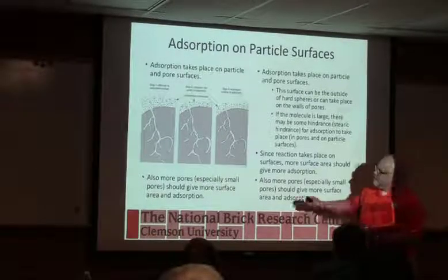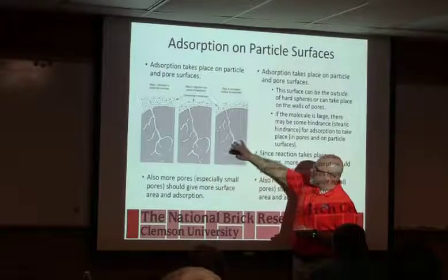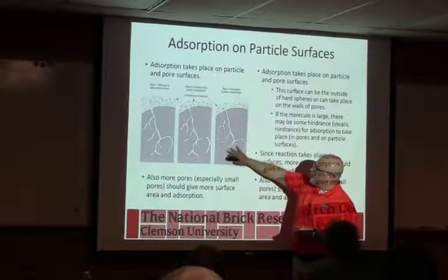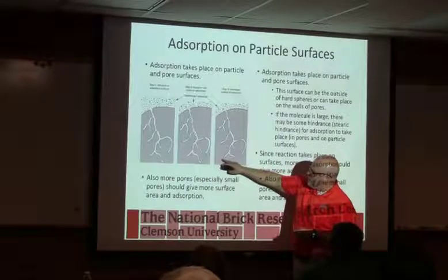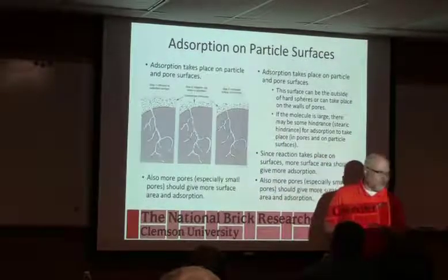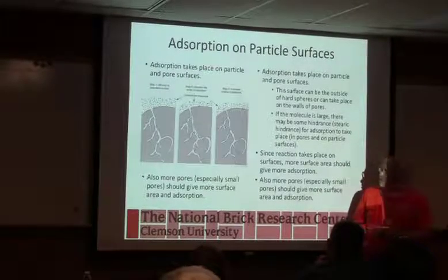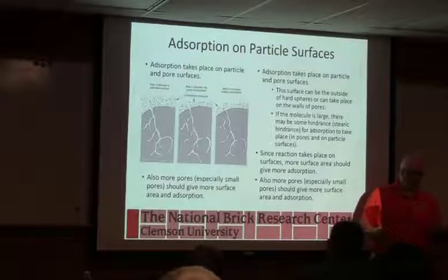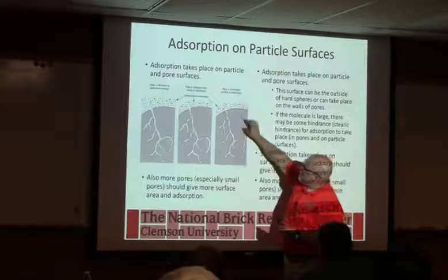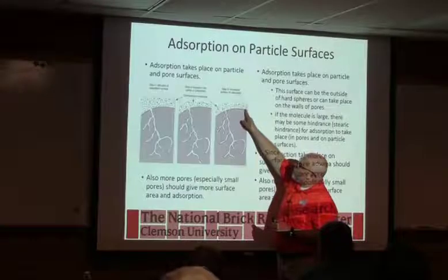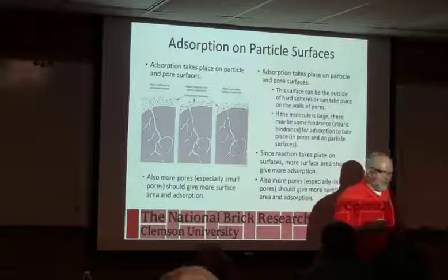So for fluorine, this helps. Fluorine will keep going through any reaction skin you get after you pick up the acid gas. Chlorine won't. Chlorine's too big. Chlorine only absorbs on the fresh surface. Sulfur also. Sulfur actually has the highest driving force to react with limestone, but because it's so big, once there's any reaction on that surface, it can't penetrate through it like chlorine or like fluorine can.